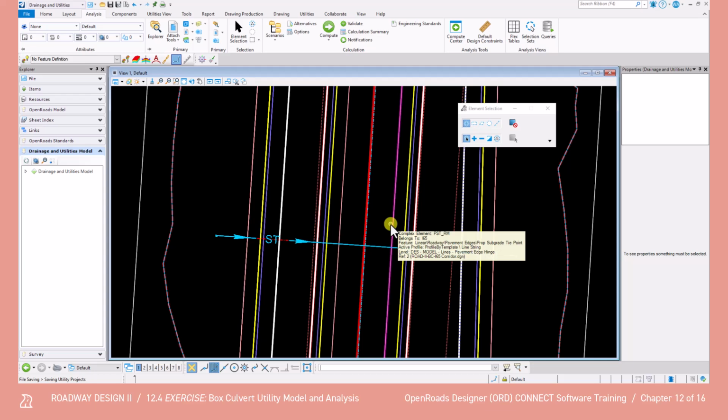However, that is the cell height and not the box height. Our box is under about 17 foot of fill, so we need to include the height of the edge beam as well. So from standard drawing STD 17-7, we will determine that the height of the edge beam is 1 foot. So we need the height of the edge beam and the ST dimension to calculate the height of the wing wall, which equates to 9.75 feet. To be conservative, we will round up and use 10-foot value for the length of the wing walls.